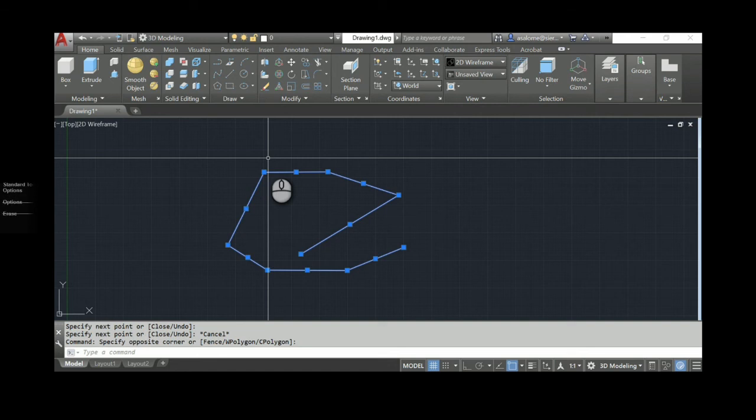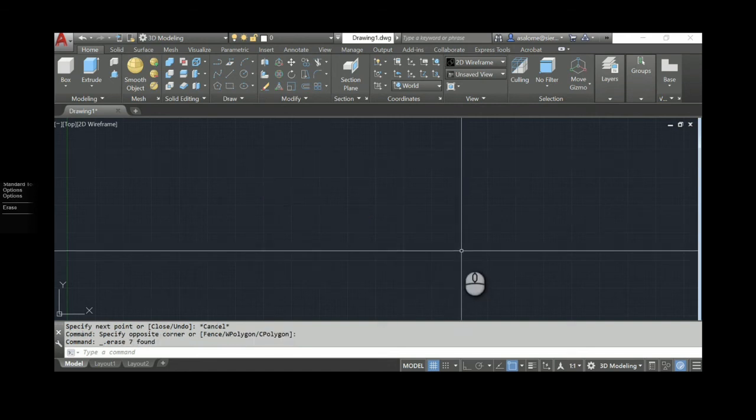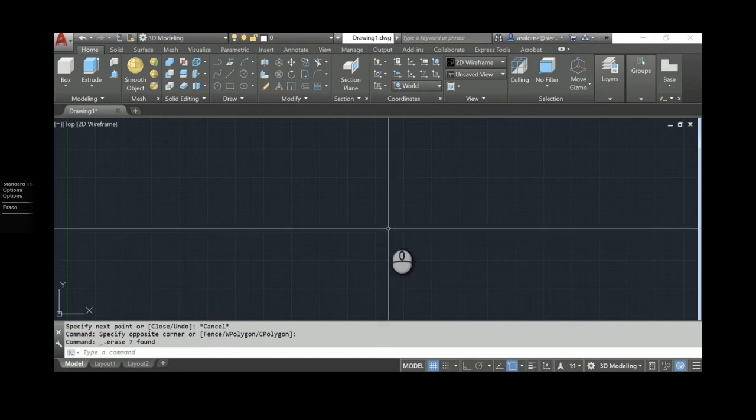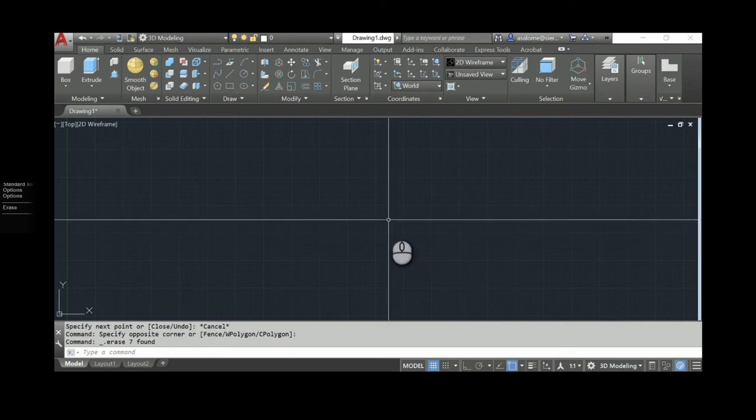I think for the most part, that's the majority of what you're going to do. Keep in mind that when you do start an AutoCAD session, make sure you're using the template that I've provided to you, because there are a few settings that I have set in that template that you're used to having set in the lab at school. Things like solid history and those sorts of things that need to be on for solid modeling are set up within that template, and that file automatically brings some of those settings in with it. So make sure you're using the template, and make a few adjustments.